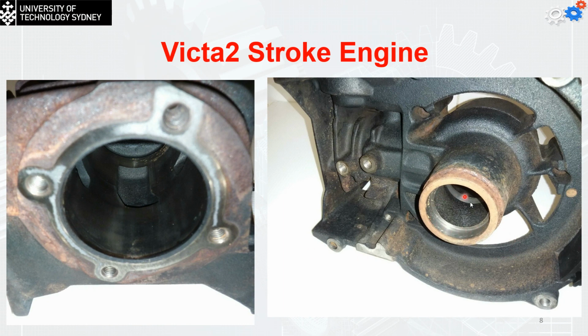This will be the bearing seat. Once again, we are going to have a critical dimension for this one, especially since the bearing is going to be fitted by a press fitting operation, just adding a little bit of force to seat the bearings in this housing.